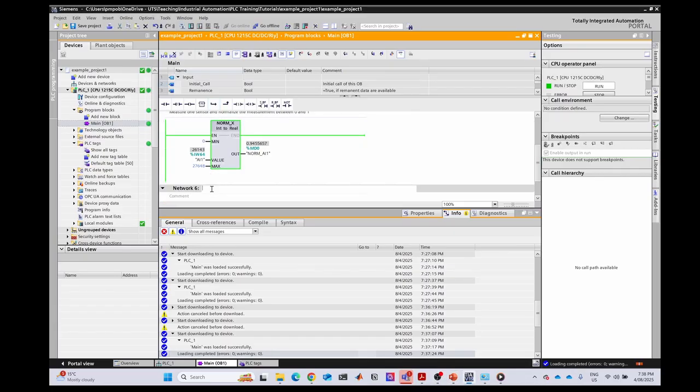Right, so now what we are going to do is pass this measurement to an analog output in order to read voltage in the voltage meter that we have in the device. So here is going to be an analog output. We want to send an analog signal to the VDC meter 1.